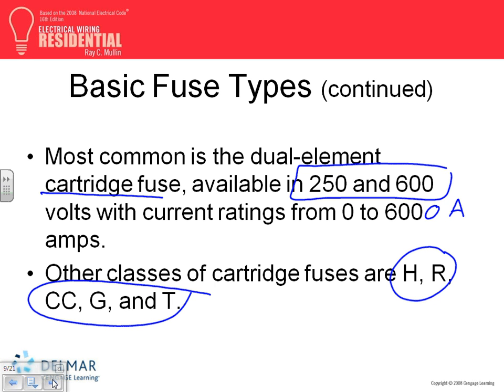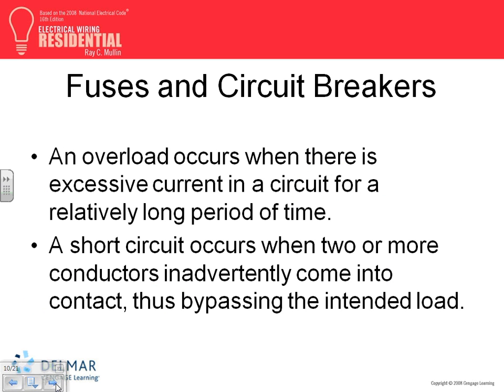They stick it into the base of the fuse, so you can't overfuse, guys. With plug-in fuses, if the socket can fit 15 and 20 amp, and I take a 15 amp fuse and put in a 20 amp fuse, what happens to the conductor? The conductor is number 14. You burn the conductor. To prevent that, they have this little S deal that you plug in to prevent you from doing that. But that's not really at the design level, it's at the electrician level.